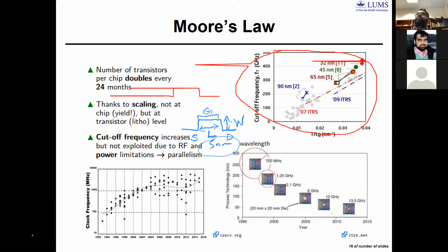So if I go to 5 nanometer, I have some power issues which come with the scaling down of technology. That's why, for analog circuits, I normally operate at slightly higher nodes, might be 45, 65 nanometers still, and I get the same benefit. In digital, when I'm talking explicitly about the processors, the processor inside a mobile phone or a laptop, that is basically where the main competition is happening, and people are going to 5 nanometer. So that is basically shown.